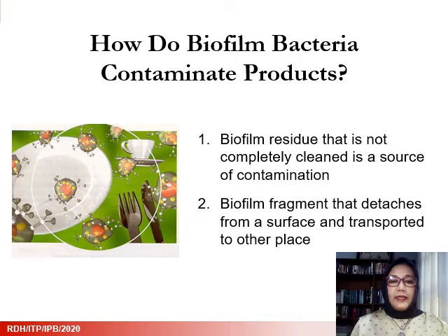How do biofilm bacteria contaminate products? One is because the residue is not thoroughly cleaned, thus it becomes the source of contamination. Secondly, because of the detachment of some biofilm fragments that are transported to other parts of the facility.